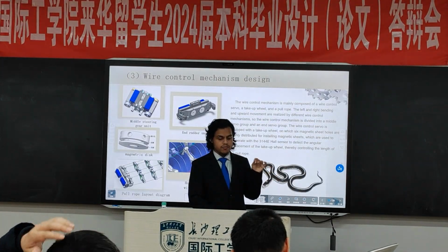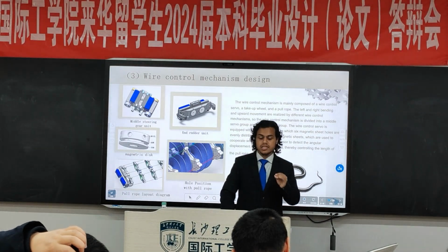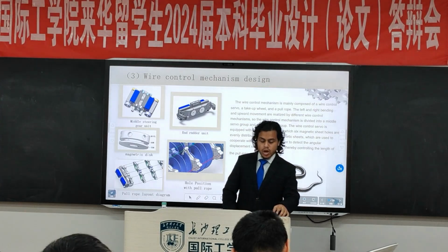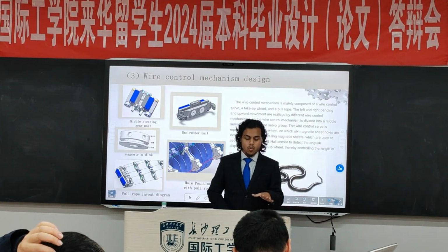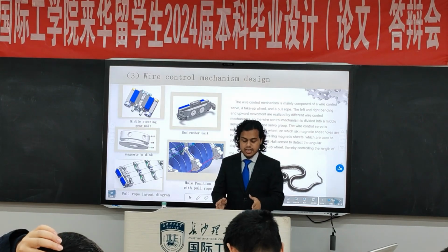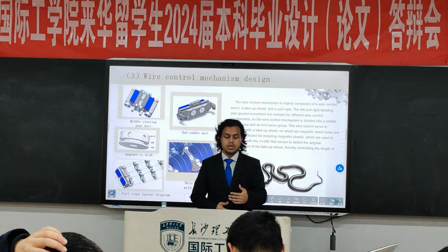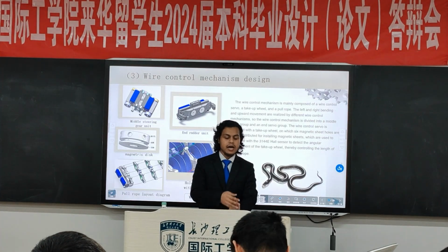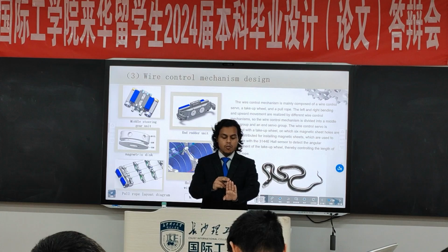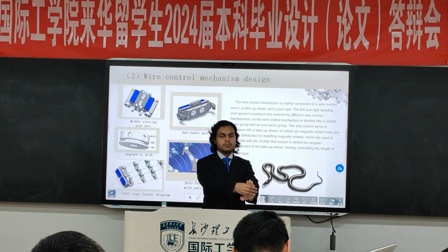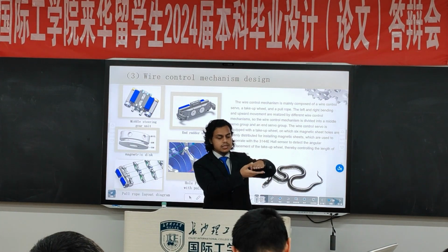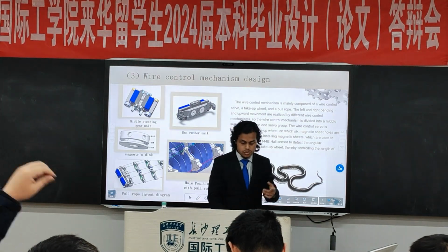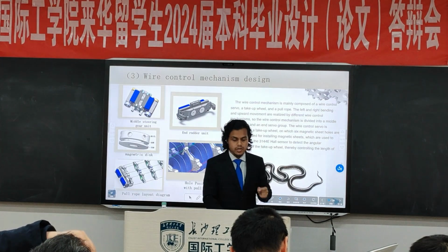The most important part of my thesis defense presentation is the wire control mechanism design. It is very important to understand why wire control matters, because when we control the snake from left to right, forward to backward, we cannot control how the snake lifts its head by the wire control system. By pulling the wire, the snake can be pulled in, like if it is like this, the snake can be pulled that way, then we can overcome this obstacle. So that's why the wire control mechanism is very important.